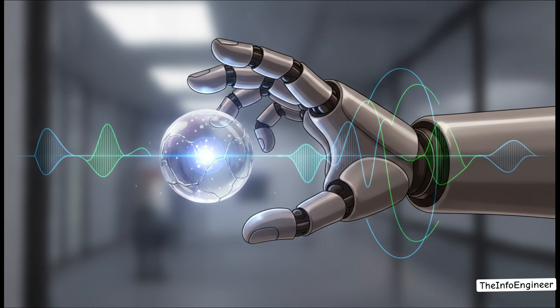It uses a proportional response to gauge the current error magnitude, an integral calculation to clear out any tiny lingering drift, and a derivative calculation to predict the rate of change and dampen the force. This ensures the system stops smoothly and exactly on target instead of violently overshooting.